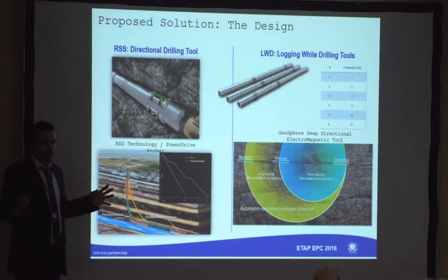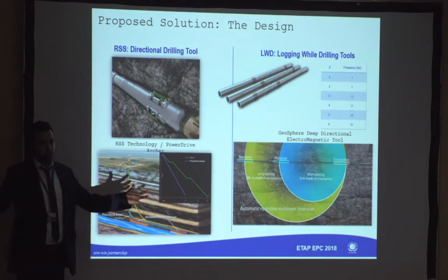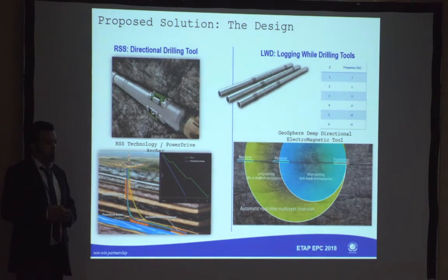And the spacing between the transmitter and receiver. So that's why we are configuring interactively our BHA to capture the maximum of signal for us. And then the third parameter is the formation resistivity, which we cannot control. So the response of this technology depends from one reservoir to another based on the formation resistivity.